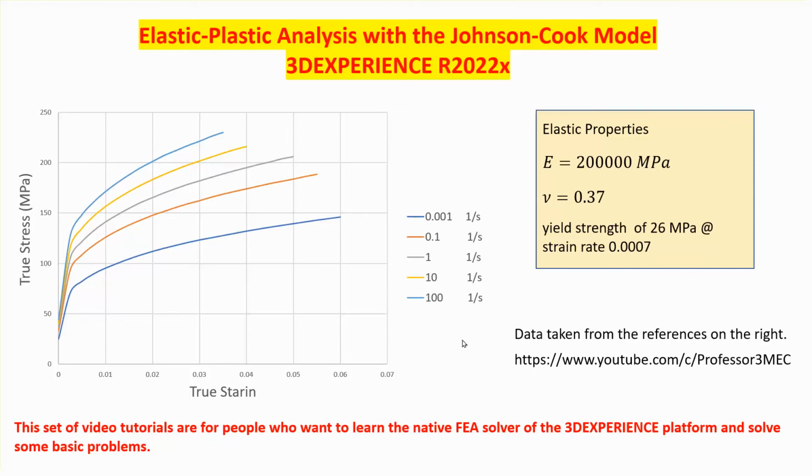In an earlier video, I did the same problem except that the information was supplied to the software in the form of tables of true stress versus true strain at different strain rates. The difference between that problem and this one is that the data that I took in the other video are fitted into the Johnson-Cook model and the parameters are fed into the software. Both the data and the parameters calculated are taken from this nice reference.